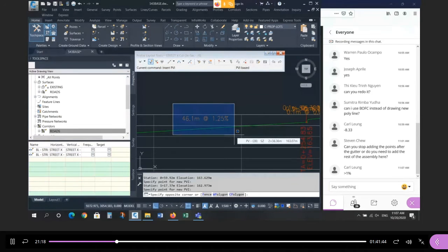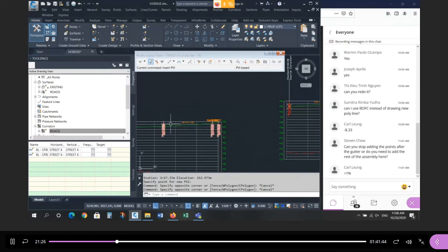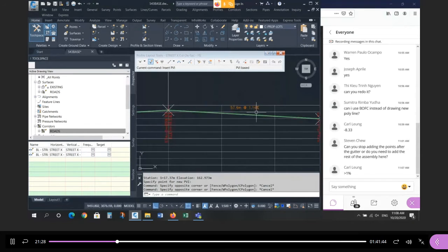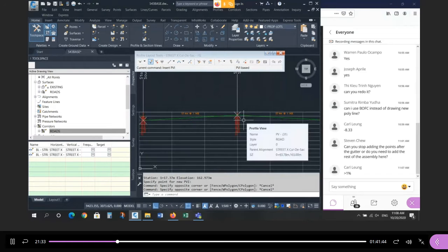So we started with 1%, we calculated what this slope should be, we rounded it up, which means the slope from the gutter all the way around both sides to the entrance of the gutter should be a little bit steeper than 1%. So again, this is not a surprise. It's confirmation that you did your work correctly before. Okay, so I'm not designing anything here. I'm just creating the explicit data required for the modeling.